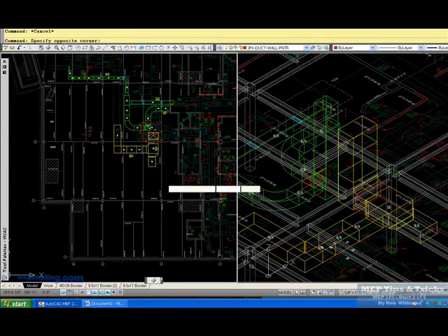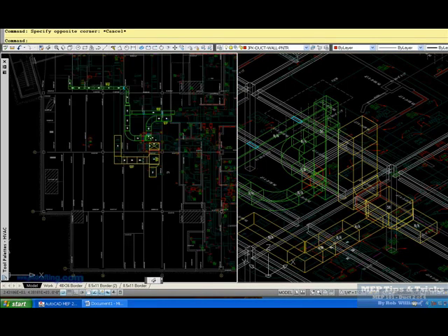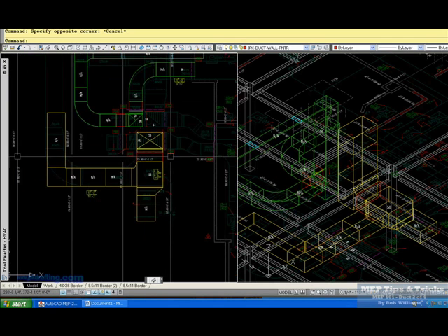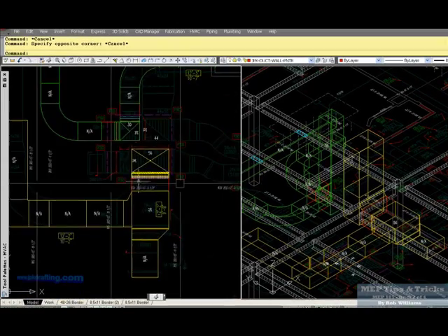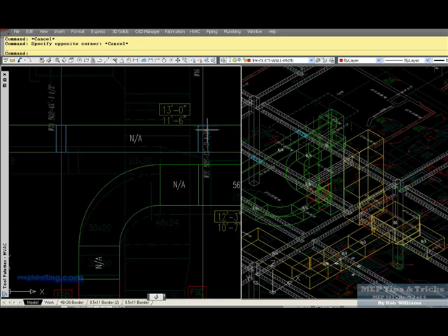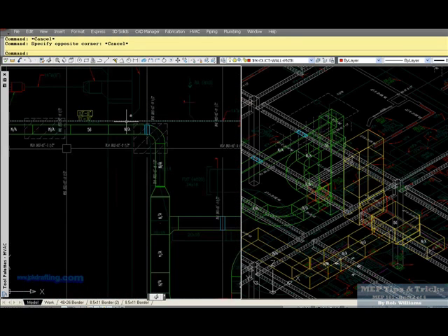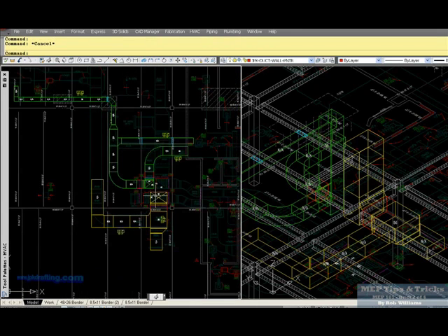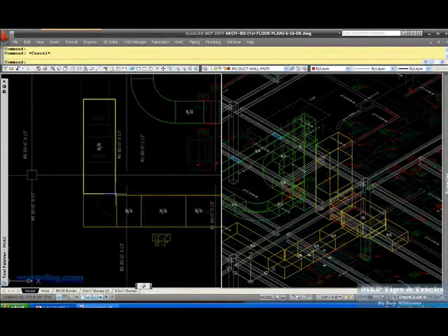Alrighty, now we're back. I think what we'll do today is review some of these fittings that we used yesterday, go into a little more detail with them, and then we'll come back. We'll draw a little bit more of this riser, and then we'll offset some duct around, like this duct is hitting that steel. This duct is going to collide with that when we draw it out. And then on the third and final duct video, we will do some detailing. I think that'll cover a lot of the fittings and what you have to do to manipulate it for shop drawings.